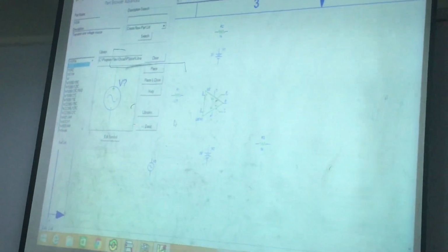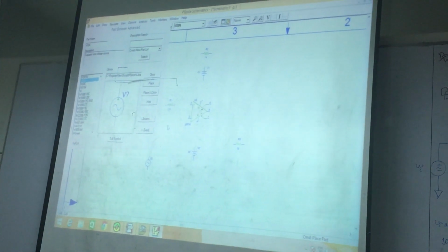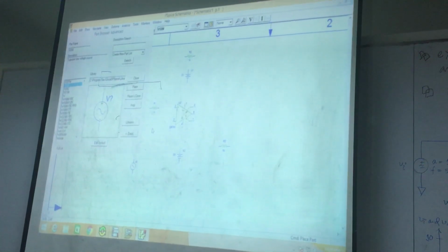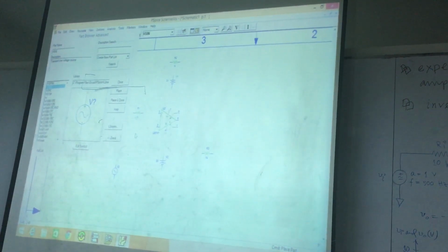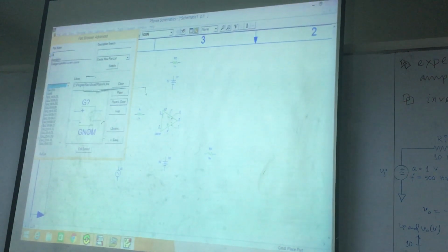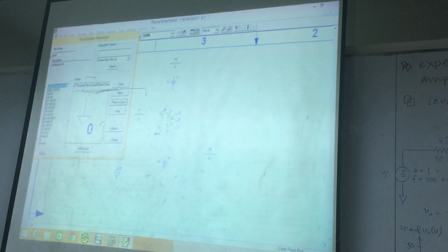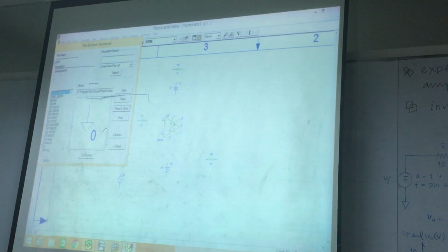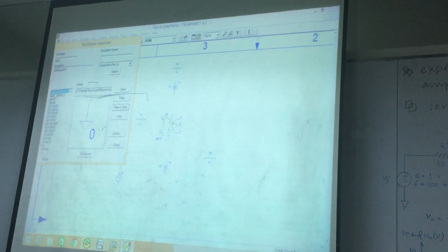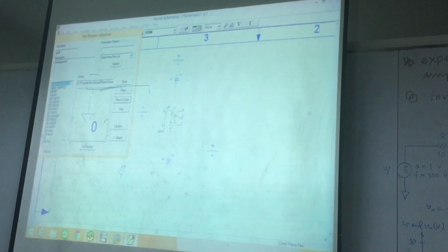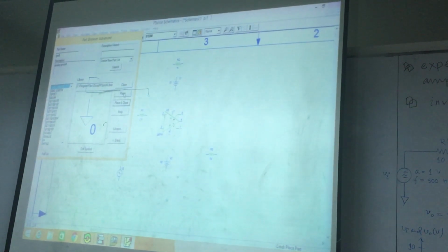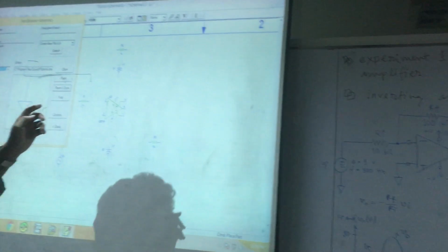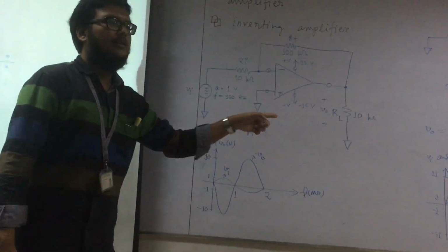Anything else? Do we need anything else? We need ground. Okay, otherwise the software is not going to work. So where is the ground? Many copies are grounded over here. I'm going to use just 1 copy known as GND_analog. You just type GND, it's going to pop up below. GND_analog. How many copies? As many as you need. How many do you see?